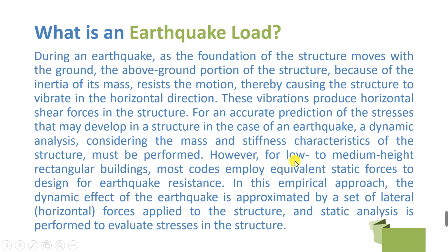However, for low to medium rise rectangular buildings, most codes employ equivalent static force to design for earthquake resistance. In its empirical approach, the dynamic effect of the earthquake is approximated by a set of lateral or horizontal forces applied to the structure, and static analysis is performed to evaluate stresses in the structure. So, anong ibig sabihin nun?